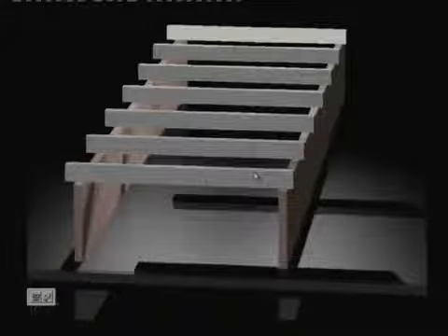You can take the end beam and the other end beam, those two end beams, and design them separately, because they will have less load compared to the inner, intermediate beams, which get slab load from both sides.